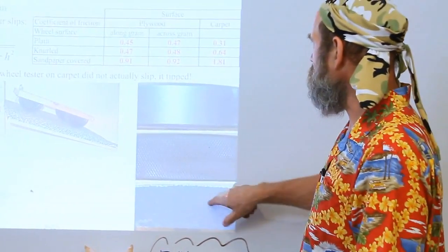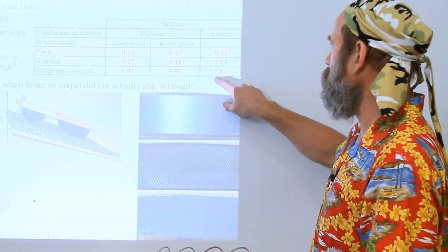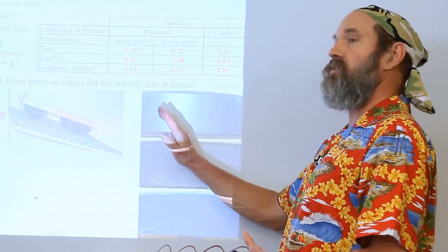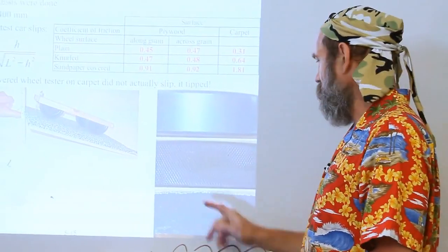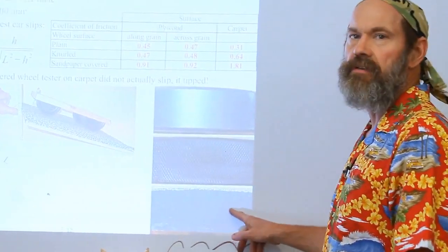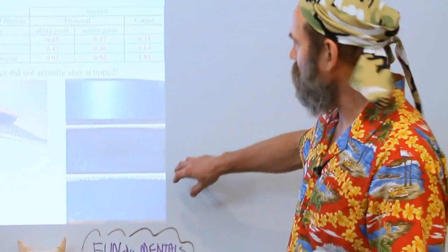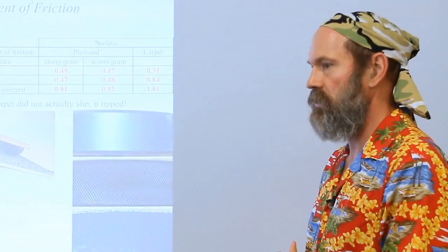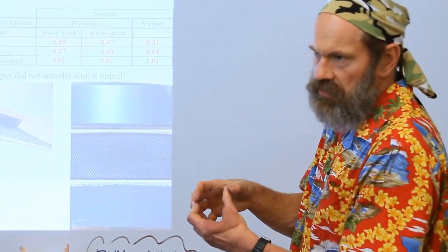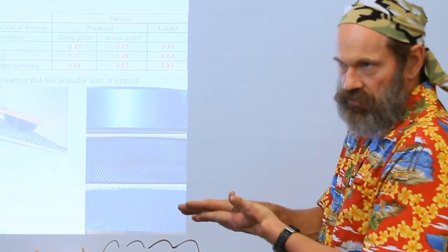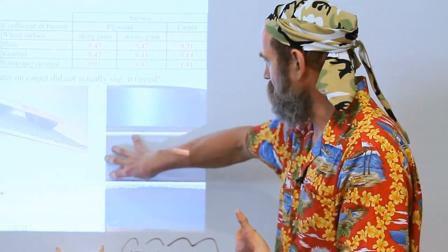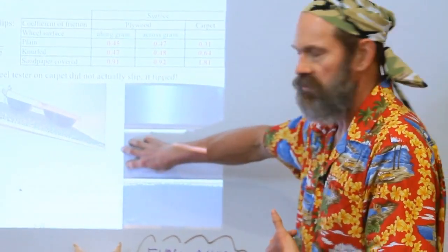Sandpaper, how come sandpaper has a higher coefficient of friction than 1? That means it should really be sliding right off. Well, this almost acts like Velcro then. Okay, so the surface finish will play an important role in the apparent coefficient of friction if it forces mechanical engagement. If it's smooth, hard surfaces, what you can do here is not a whole lot.